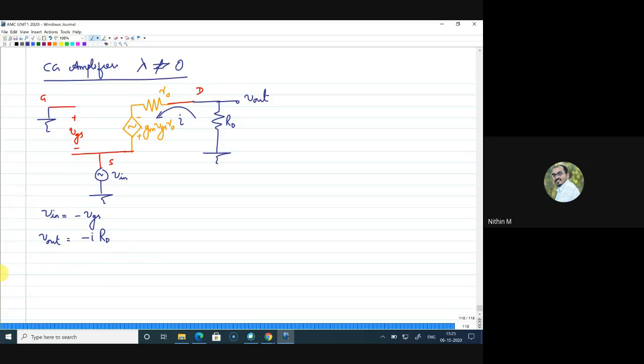So I is the current here. Previously, in the case of common source with degeneration, if you remember, you had a resistance here as Rs. In that case, we wrote the current as the single voltage source divided by the sum of the resistances; the three resistances were there. But now it is not the case. You can try in different ways, so let me write an expression for that. Current is flowing in this direction, I into Rd.